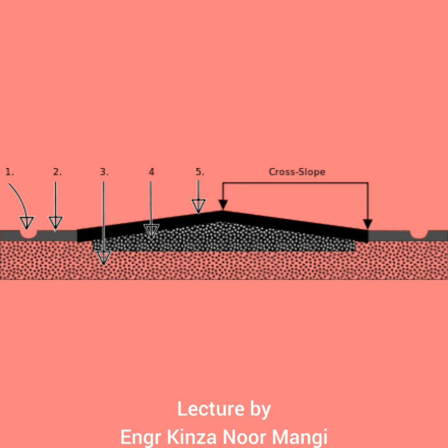Coming towards cross slope. Cross slope is also known as camber. Cross fall is a geometric feature of a pavement surface. It is the transverse slope with respect to the horizontal, and it is very important for the safety factor. Cross slope is provided to give a drainage gradient so that water will run off from the surface to a drainage system such as a street, gutter or ditch. Inadequate cross slope will contribute to aquaplaning.